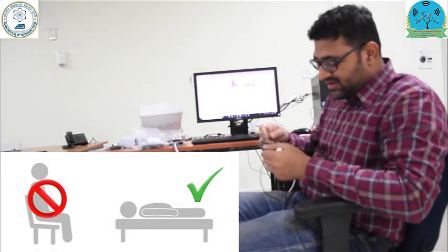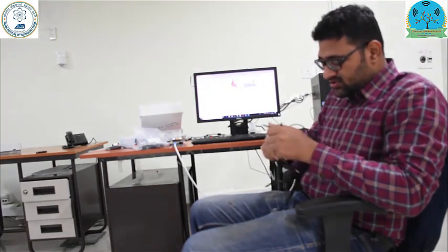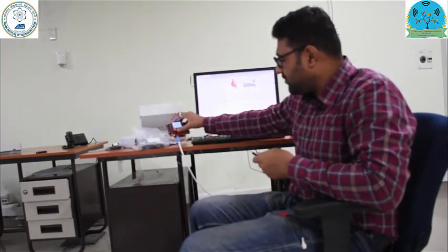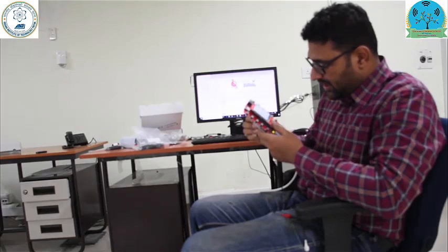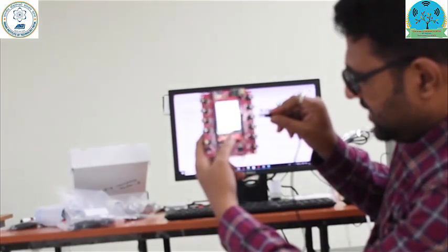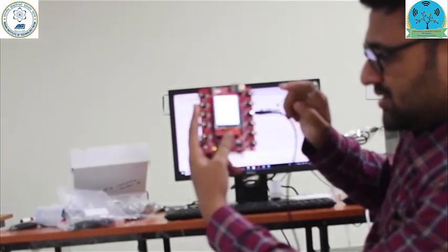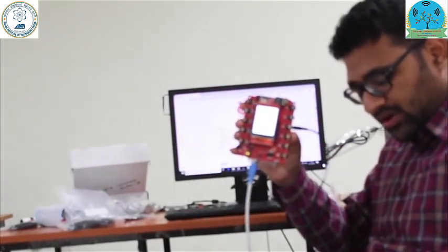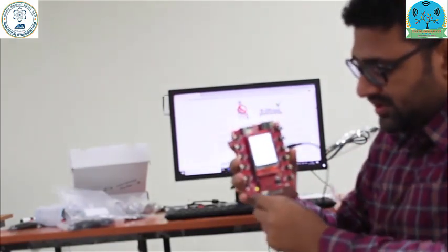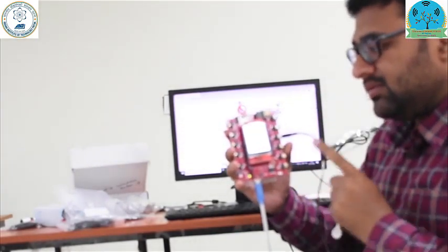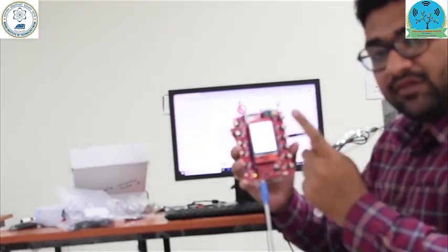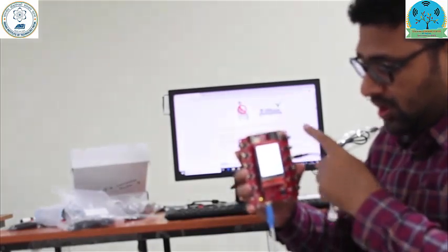We can use this as a wired sensor also, and as I discussed before, this wire cord should go to the right channel in the MySignal platform. So this is the MySignal platform, and as I can see here, the ECG part goes onto channel number 3. Only if I connect to channel number 3 for the ECG signal can I monitor the ECG of a person. It is very important to understand that for the MySignal Kit, the channel is fixed for which port we should deploy which sensor. So ECG will always go to the 3rd port of the MySignal Kit.